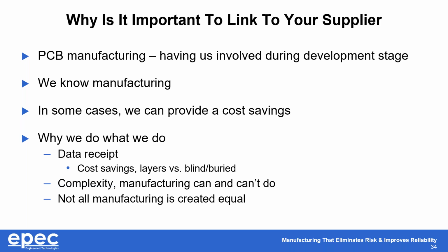Like I said, the material suggestion, you may come back with some exotic material that's not commonly stocked, and we can say, well, rather than this, although we can get it, there's a 12-week lead time, if you use this, it'll give you the same PCB for a lesser cost. It's repeatable, the material's commonly stocked, and it won't be hard to get from lot to lot or from order to order.